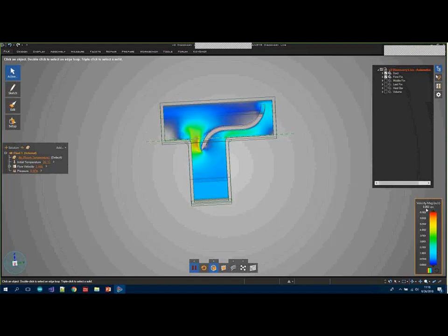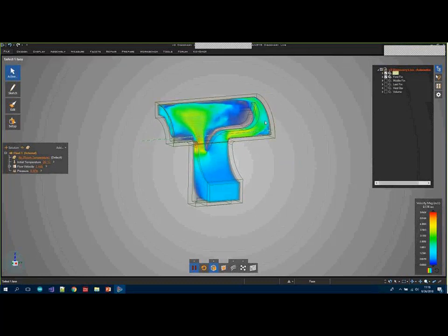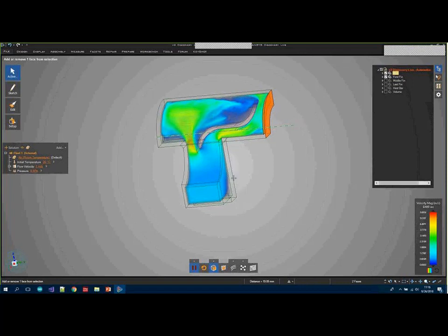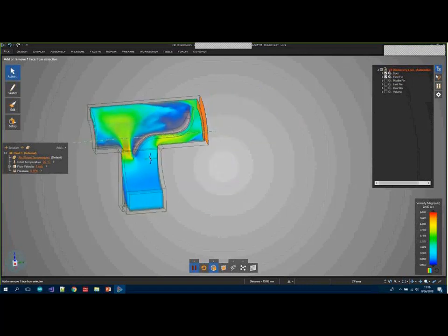You can see the amount of time that has elapsed within the simulation from the legend. So, of course, it's going to be a little bit slower than real time, but you can see it here. So we're at about a quarter of a second, and we can see the flow adjusting to that change. Other things that I can do are I can update the entire body itself if I need to extend it. So in this case, I'm going to grab the two faces of that duct, and I'm going to use the move command.